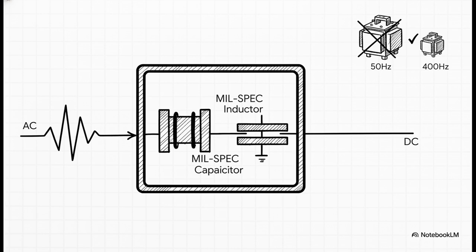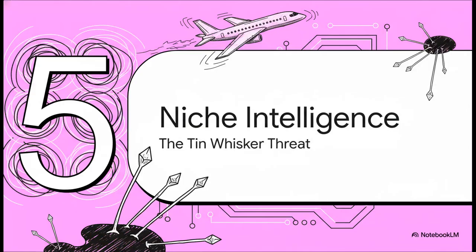Inside the TRU, heavy-duty MIL-PRF-27 inductors and MIL-PRF-39018 capacitors are integrated into a robust LC low-pass filter. This network's entire purpose is to smooth the rippling 400 Hz rectified output into a pure, flat, 28-volt DC for the aircraft's main buses. We conclude with a non-obvious but critical threat in modern avionics: tin whiskers, a problem rooted